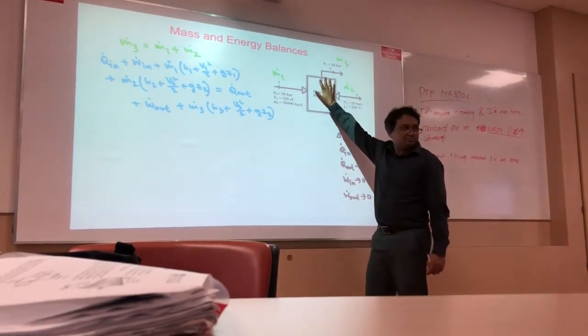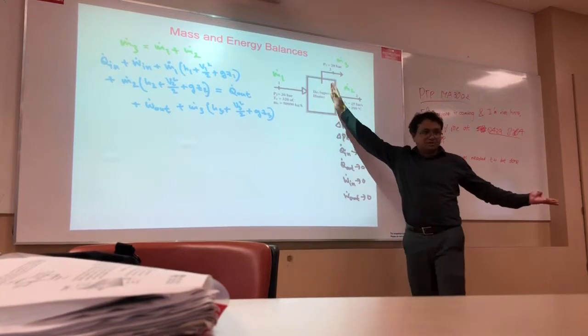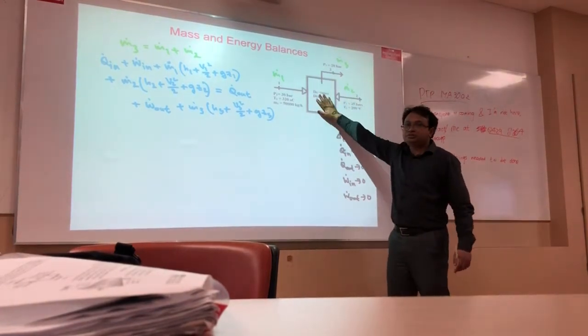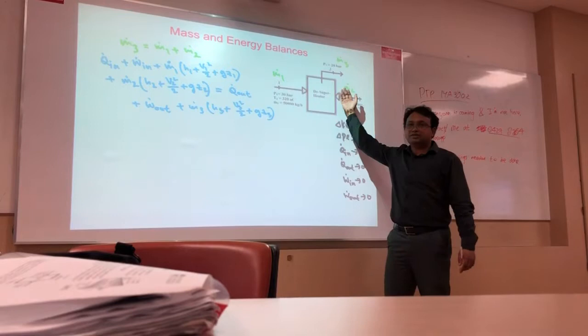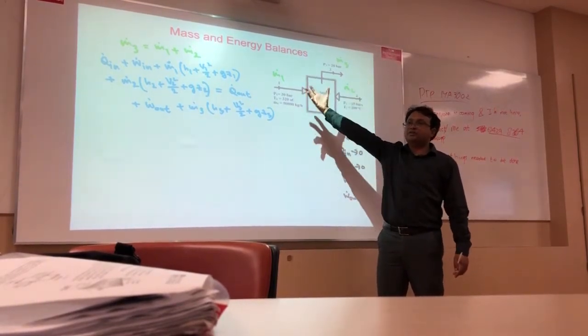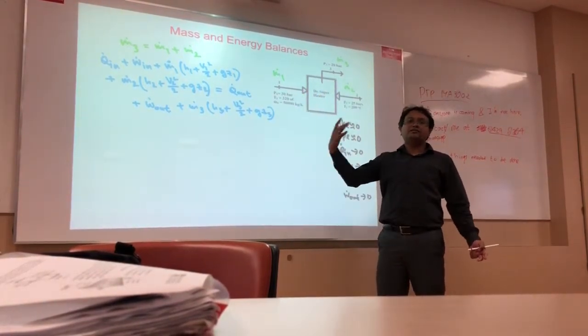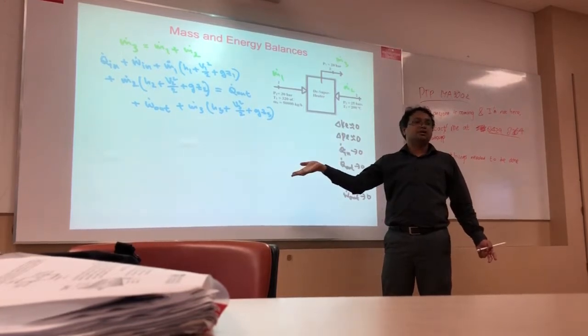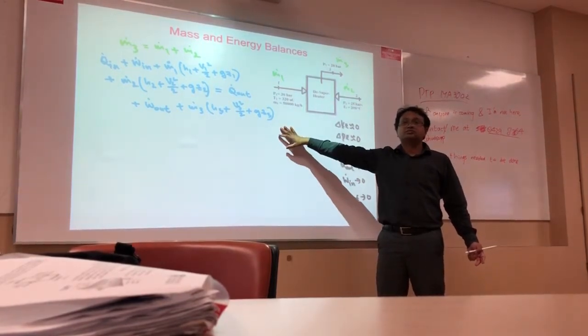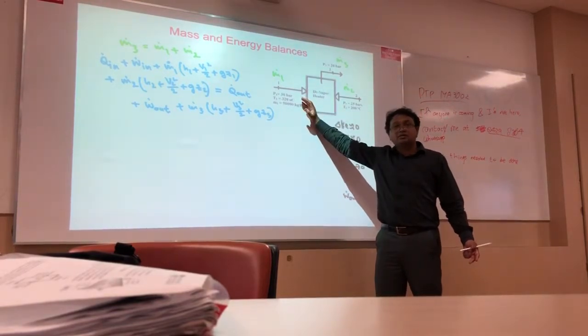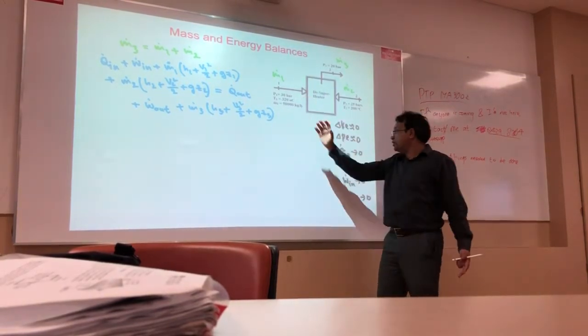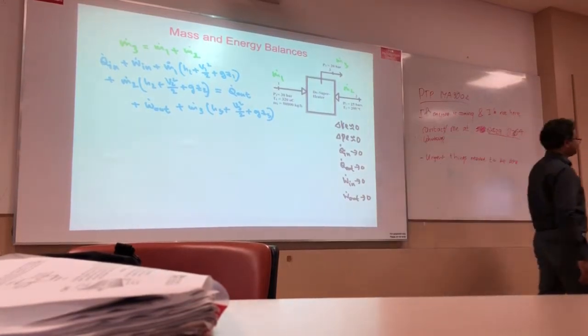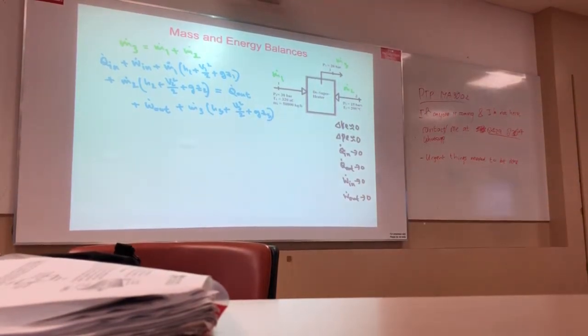Same thing, because this is an insulated chamber, the fluid enters the chamber, they mix together, and vapor is generated. Very simple. Here, the fluid brings energy only. There is no external heat source, and the system doesn't lose any heat. You have to understand this, otherwise you cannot solve the question. Then I can say this is 0, this is 0.